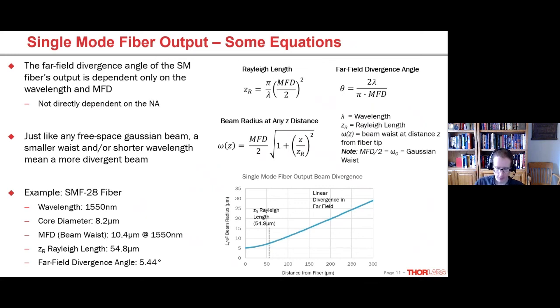Usually when you have those stress rods in the fiber, the core ends up being elliptical as well because they kind of squish the core. So you're probably going to have a slightly different mode field diameter at the slow and the fast axis. And you have to look at those two orthogonal polarization states separately, versus what we're talking about here, where everything is averaged together. So that's some of the differences there.